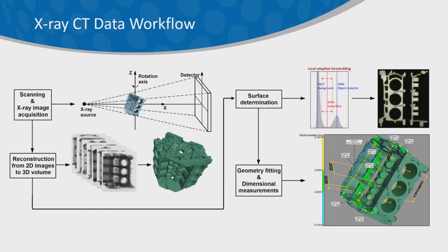One of the most important things in the measurement domain is we can threshold it and actually fit a surface to it. And we'll show a quick example on the next slide from that. But once we have that volumetric file and that surface on it, then again, we can treat it essentially as a CAD model or a point cloud model and do all these very, very precise measurements on it.